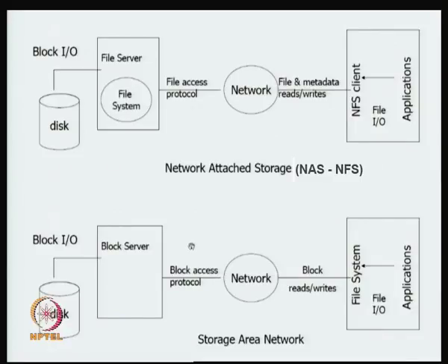Normally the problem with electrical connections is that, for example, if you have 32-bit transfers, you need 32 electrical lines, and there's a problem called clock skew, which creates problems. Therefore, what people like to do is to go for serial protocols. Ideally, what we want to do is to take the SCSI protocol, encapsulate it into a serial communication medium and then interconnect things. So, that's one way to do it.